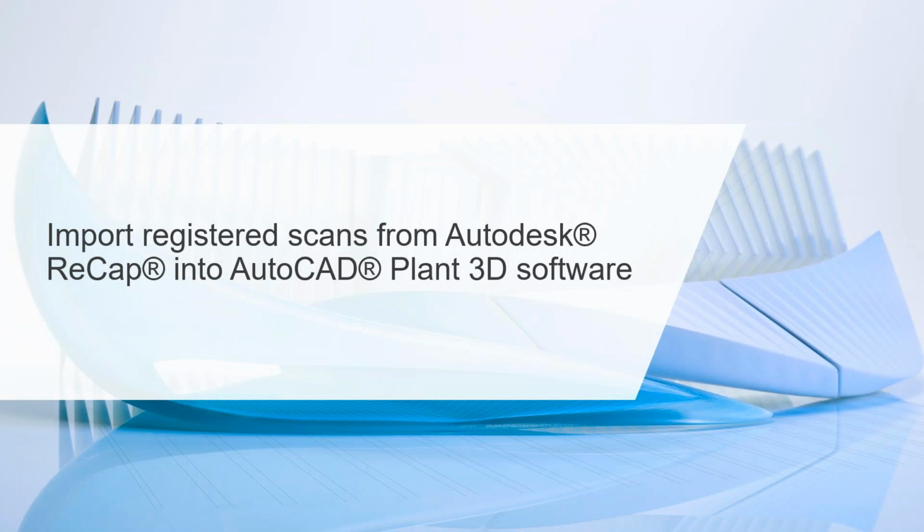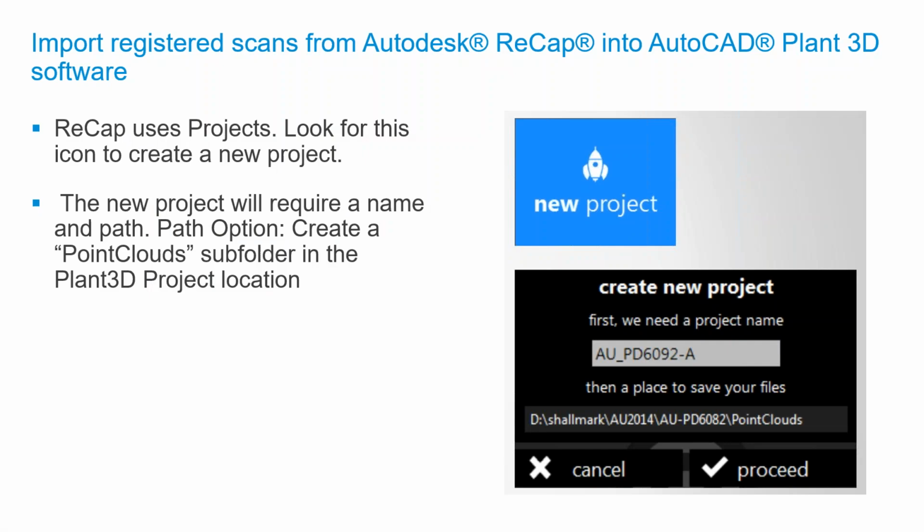So let's understand how this process works currently between ReCap and AutoCAD Plant 3D. I'll talk about how to import these registered scans and how the process moves on. First of all, if you've got any scan to BIM projects, or you're converting as-built to BIM projects, and if you're using the AEC Collection for that matter, please install the tool Autodesk ReCap Pro.